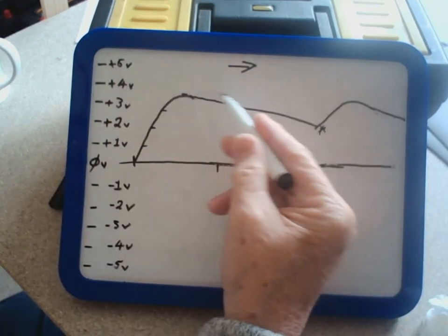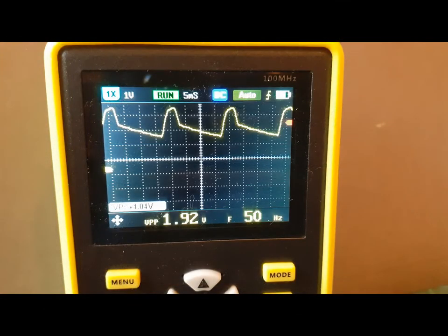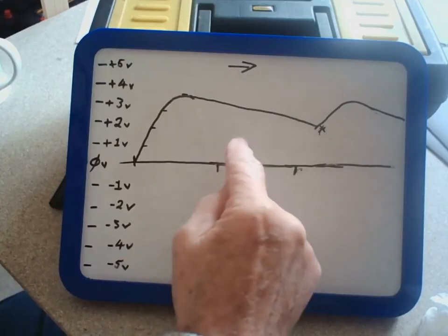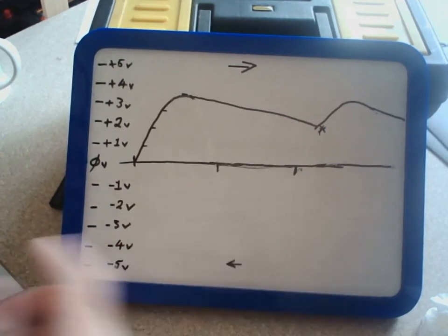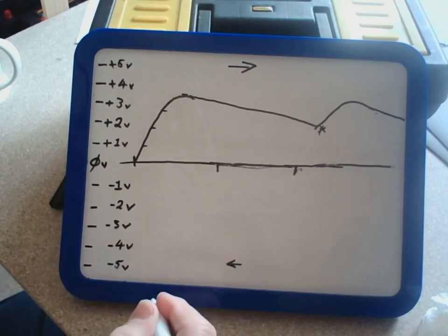And so that was the odd shape that we saw on the trace of the oscilloscope, but that also made sure that the bulb burned a lot brighter because it wasn't spending any time without any voltage getting to it. So that is how a capacitor, sometimes called a reservoir capacitor in the old days, these days it's called a smoothing capacitor, assists the production of electricity from a power supply unit.